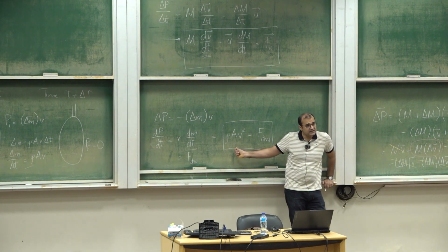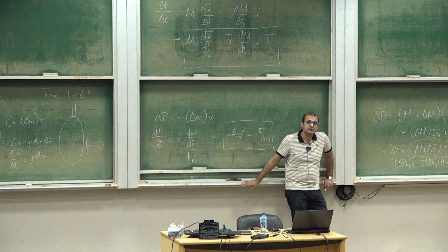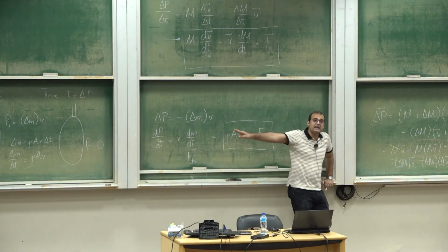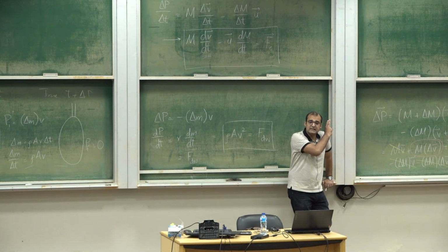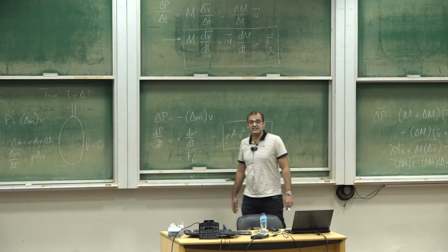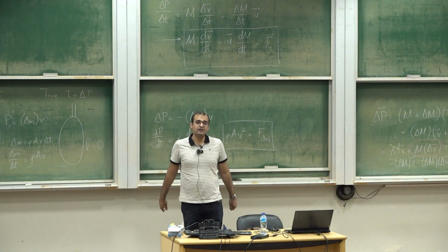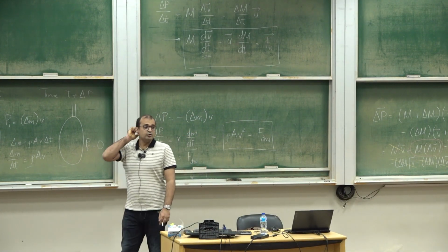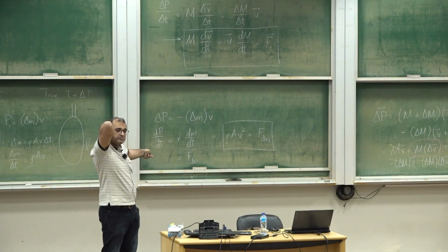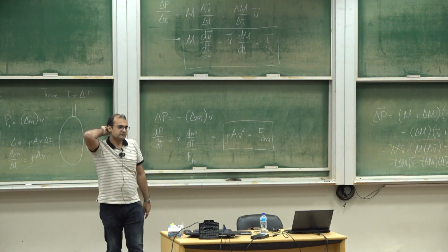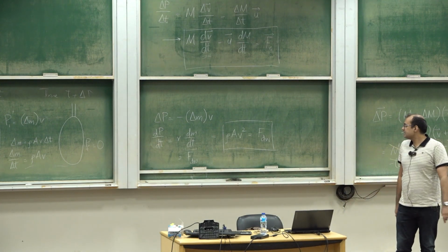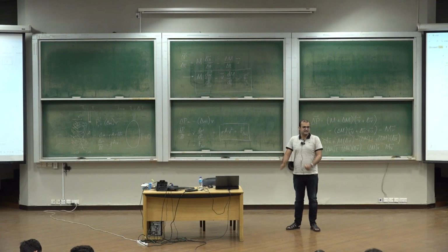If you double the wind speed, the force exerted by the wind increases 4 times. It doesn't double. क्योंकि एक फैक्टर v आया कि जितनी ज्यादा v होगा उतनी ज्यादा आके हवा लगेगी, और जितनी ज्यादा v होगा उतनी ज्यादा हवा का मोमेंटम भी चेंज होगा, क्योंकि उतनी ज्यादा स्पीड से इनिशियली ट्रेवल कर रही थी, उतनी ज्यादा ब्रेकें लगानी पड़ेंगी हवा को. Okay, so there are 2 factors of v that come in. The v goes into delta m, v also goes into m times v, momentum mein. Okay, so that's why the force exerted by the wind on the disc is proportional to v squared.